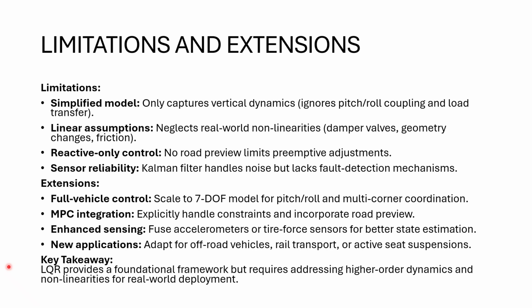Also, this is a reactive-only project, meaning without road preview, we can't really make preemptive adjustments. And while the Kalman filter improves sensor reliability, it lacks fault detection capabilities. So that is also a limitation that we have in the Kalman filter.